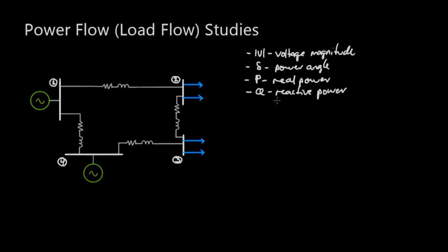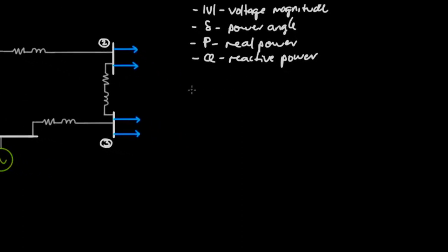And so when we talk about power flow studies, we're going to have three types of buses. In other words, every bus in the system is going to fall into one of three categories. And these are what's called the slack bus, S-L-A-C-K, and sometimes that's also called the swing bus. So let me write it over here in parentheses, swing bus.